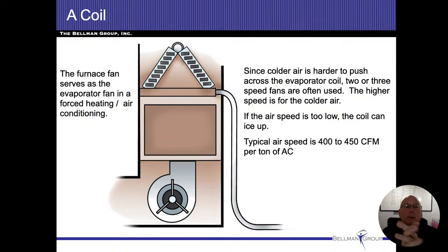The indoor coil, some people refer to that as the A coil. It only gets its name because of the shape that it's in right now. Because it's up and down like the letter A, that's the only reason why we call it an A coil. The true name, and the name I want you to remember, is going to be evaporator coil. And mainly because this is where we're converting again from a liquid to a gas. So we're vaporizing, so we're going to call this the evaporator coil.